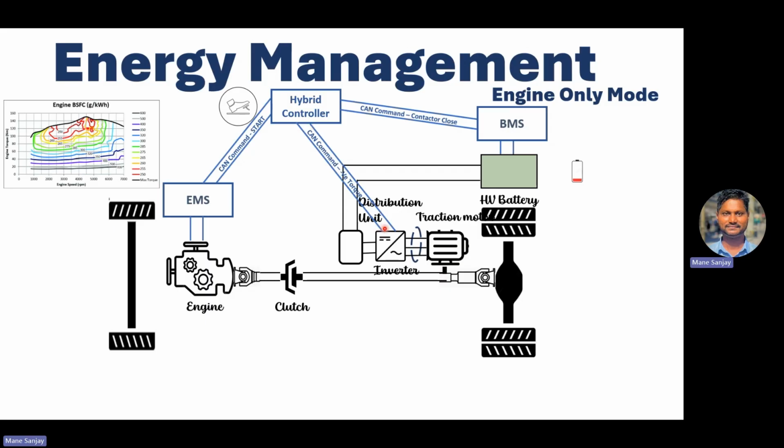So accordingly it loads that engine to charge the battery. So what happens here? During this, the battery gets charged also, right? The power is fed to the vehicle as well as the same power is taken through this shaft by this traction motor, and the motor works as a generator, and this generator power is fed back to this high voltage battery, and here the battery gets charged.